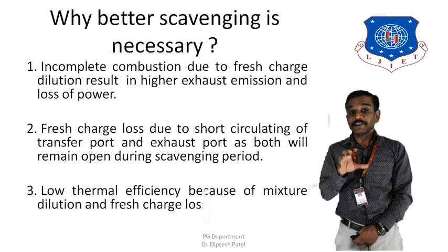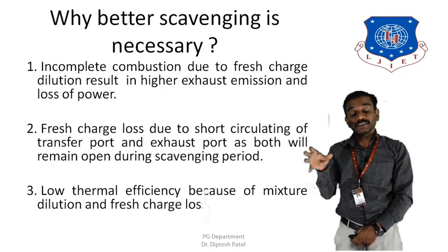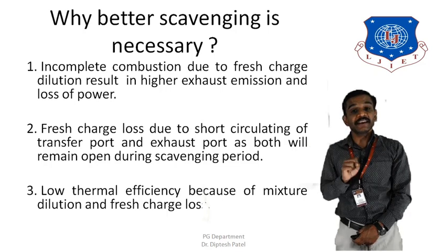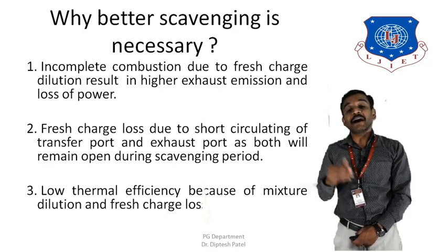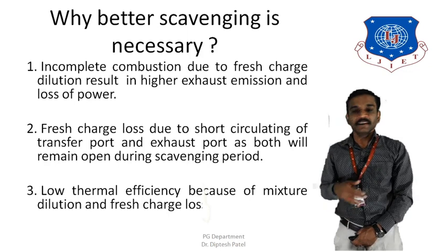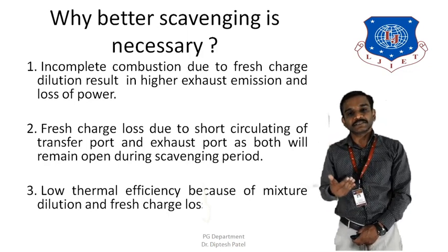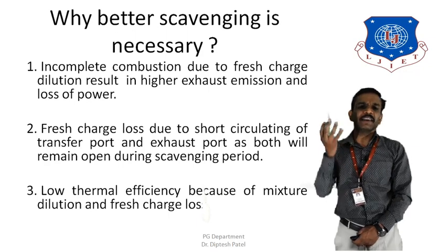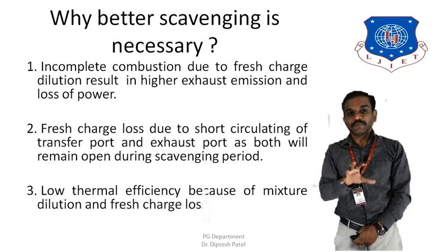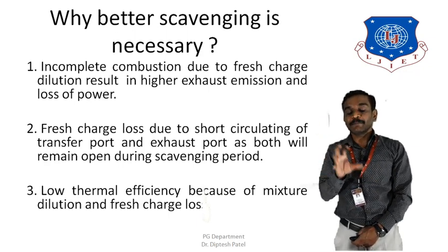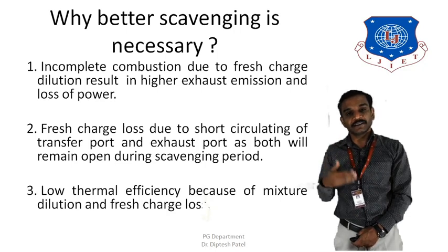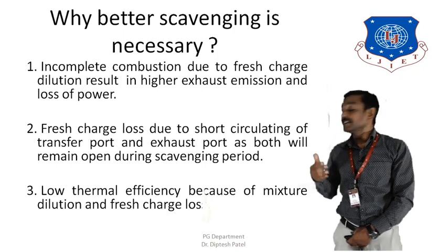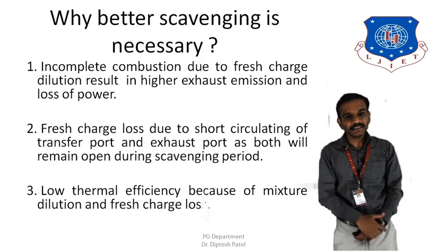If they dilute the fresh charge, the fresh air and fuel mixture, then the overall power would be reduced, and even the emissions, the pollution coming out from the engine cylinder, would increase. Therefore these incomplete combustion gases need to get out of the cylinder.